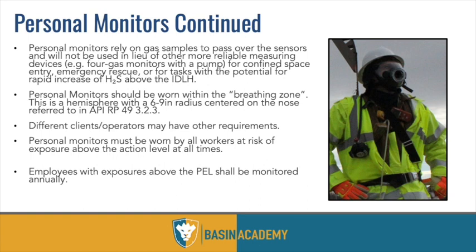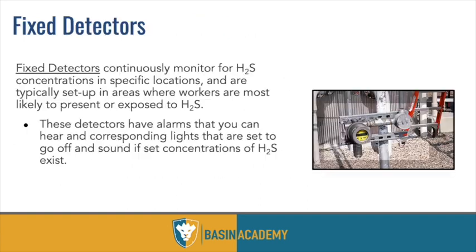Personal monitors must be worn essentially by everyone out here that is at risk of H2S exposure. Which, again, it's in every well. It's on every well site. It's in every ounce of crude oil. It's in every CFM of gas. The question is not is H2S present. The question is how much H2S is present. And that's really the main function here. So anyone who's exposed over the PEL should be monitored on an annual basis, making sure that they're not getting sick over time.